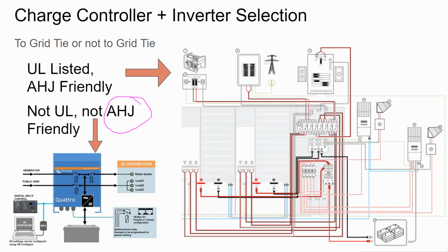We saw that example yesterday, where the most egregious example is they add an additional $15 a month to your bill because you have an interconnected solar array. This particular battery inverter can be charged from the grid, and even if it is just a one-way inverter, your AHJ may have their own opinion on what a grid-tied solar array is, and that could be a reason to go off-grid.